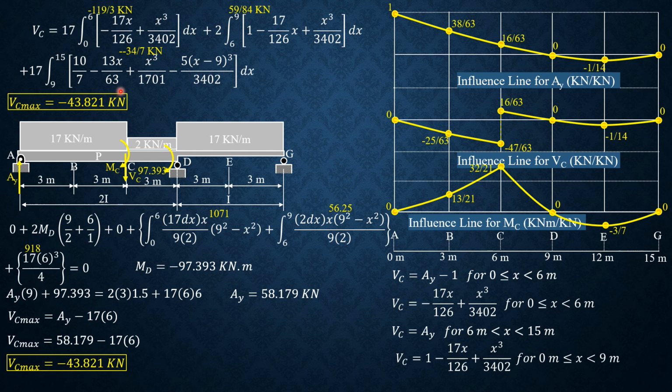So in other words, since it is challenging to derive the expression for shear or moment at a point as compared to the technique by Muller-Breslau, after knowing where to place or to position the dead load and live load, or the dead load alone, then we just analyze the beam, continuous beam, by the 3 moment equations. Then after that, we draw free body diagrams involving the required function or redundant. Then we solve for that redundant by statics.